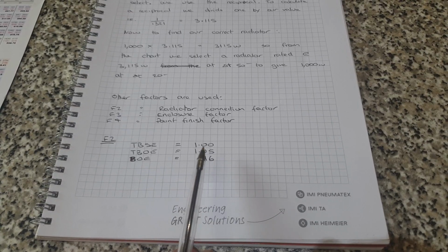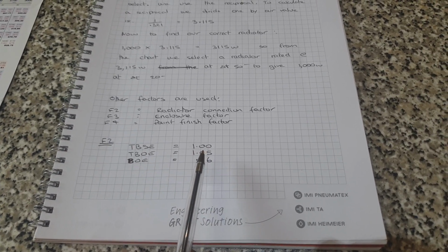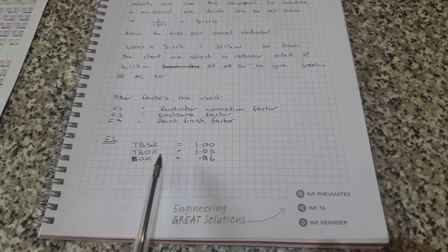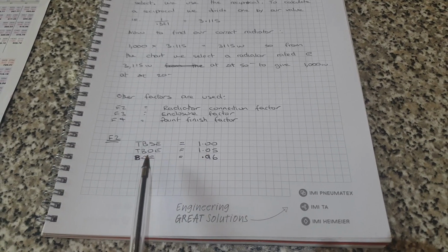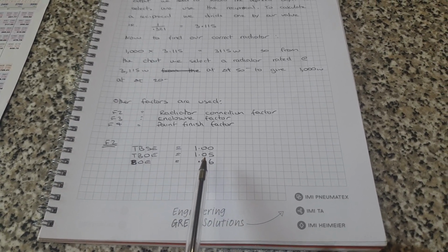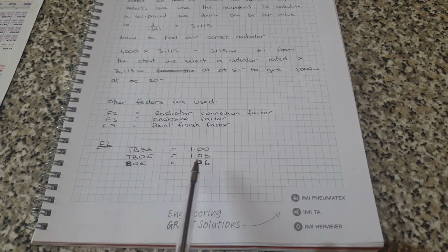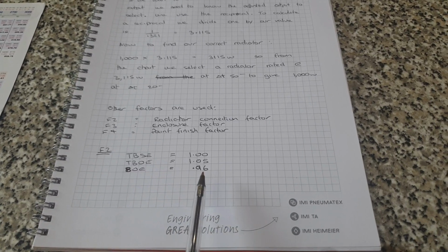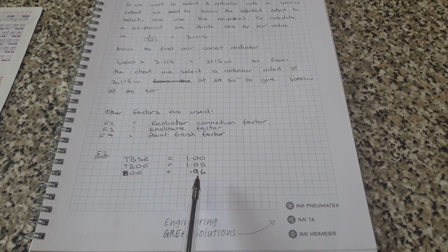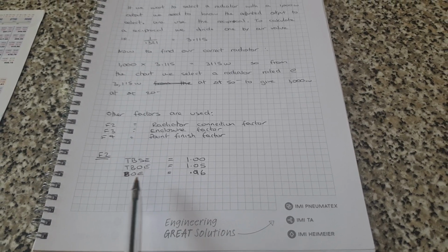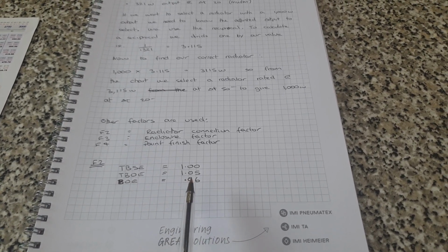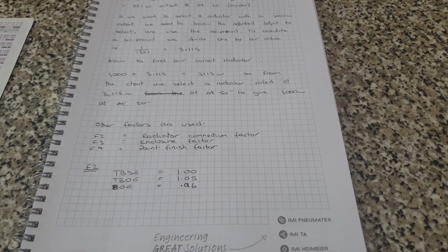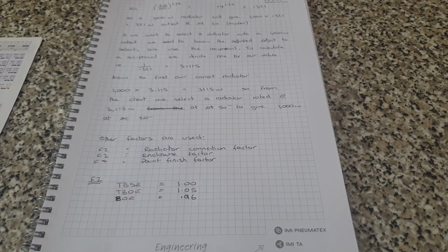And the radiators are designed, the output of the radiator is rated for this connection method. If you connect top and bottom opposite ends, you get the better output from the radiator. This is the best way to connect for full output, but it makes very little difference. And if you connect like we do in England, we're reducing the output by going bottom opposite ends. And we need to increase the size of our radiator a little bit in order to compensate for this connection method. So it's not significant differences, but I find this one quite interesting, so I'm happy to talk about it. Okay, I hope that's clear.